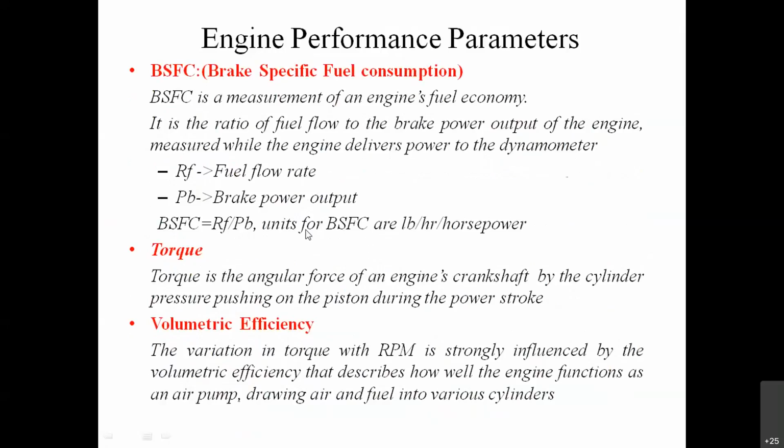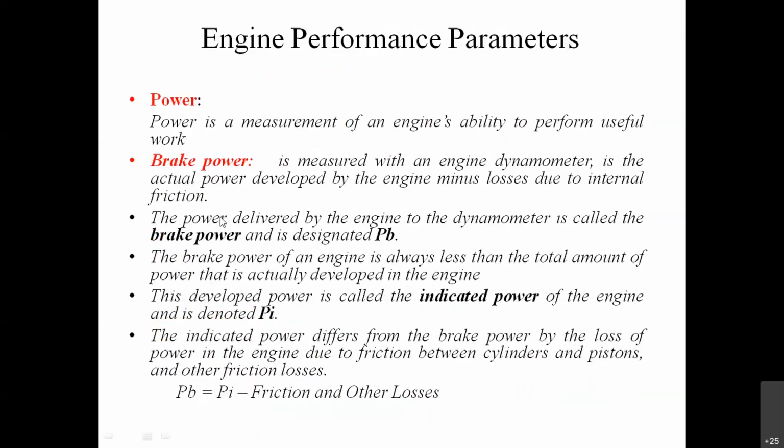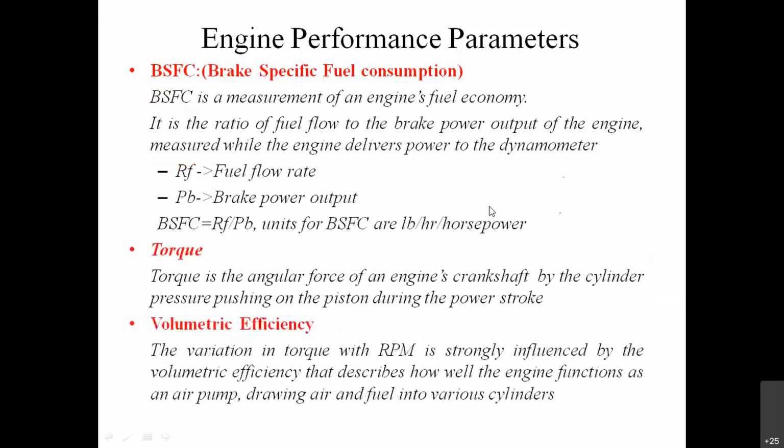Brake power is measured using an instrument known as a dynamometer, which is connected at the drive shaft. Using this instrument, we change various settings, like the load and speed of the engine, and check for different values of load and speed what power is generated by the engine.